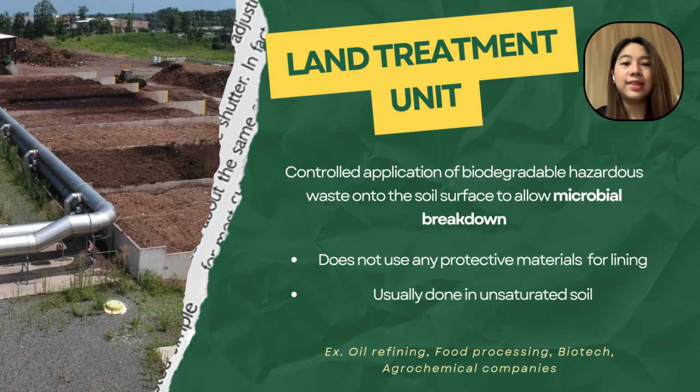Next up is land treatment units, or LTUs. They are more environmentally integrated. They treat hazardous waste by applying it to soil surfaces where natural microbes and sunlight help break it down. These processes work best in the unsaturated zone. That's the land above the groundwater table.